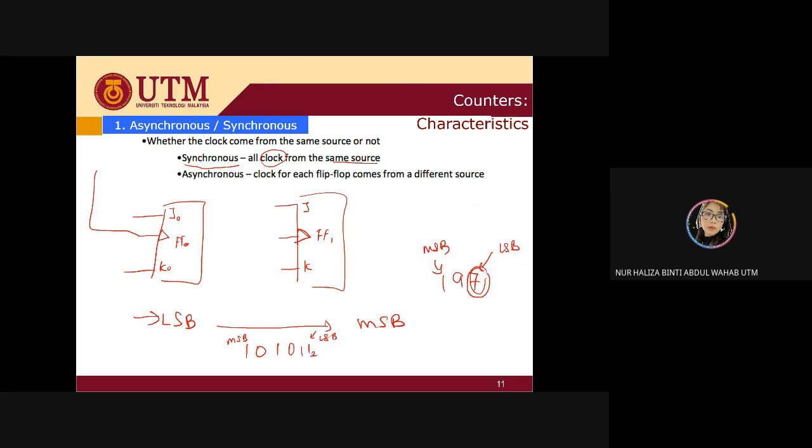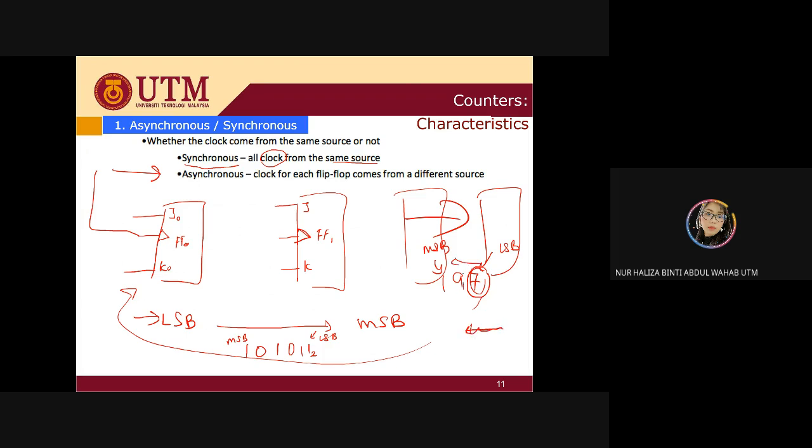So this LSB will start at the beginning, and then you're going to connect, cascade, from left to right. But for your numbers, you're going to write following LSB until MSB. Now about the connection, you have here Q, here is Q bar, Q0, Q0 bar, Q1, Q1 bar.